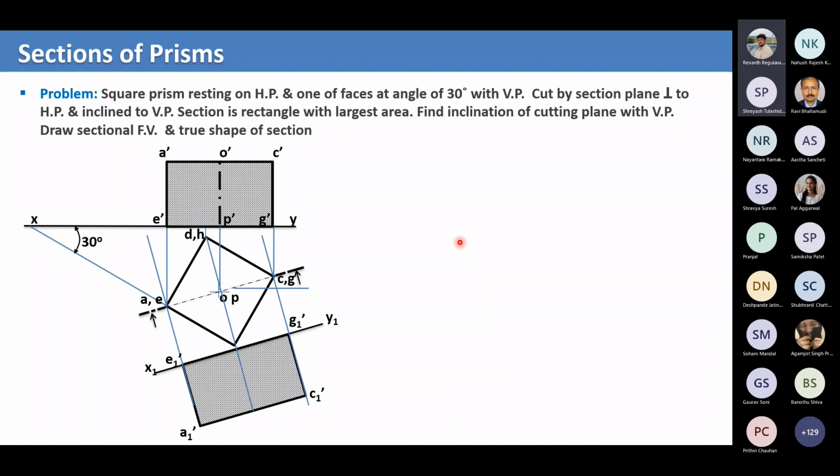Yes, but when you project it on the front view, what will happen? That area will be very small. Yes, this will also be a little small, right? Let me say one thing here itself. I'm sorry to cut in. Basically, when you choose the cross-sectional plane, always choose a plane where you can see a larger projected area. If you have a choice between a smaller projection area and a larger projection area, choose the larger one because it's closer to the truth. That's all. Yeah, Jayant, go ahead, please.